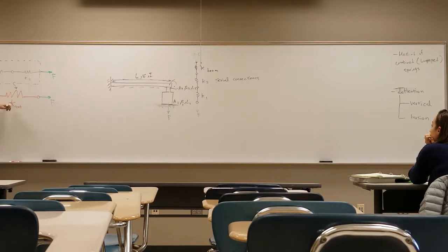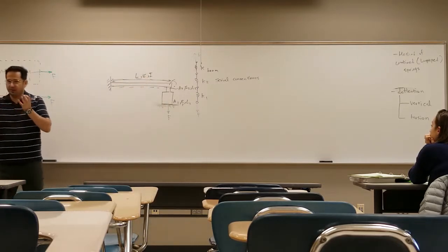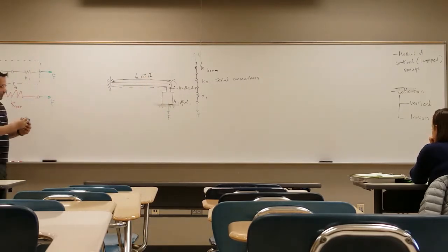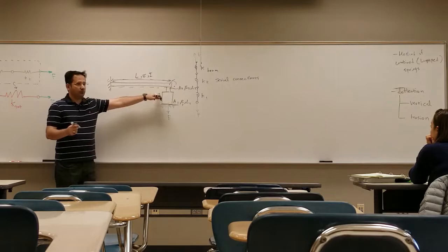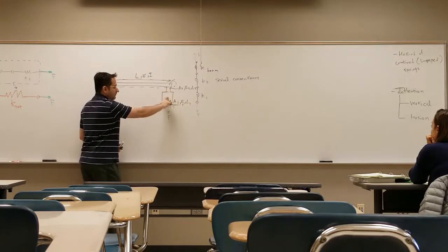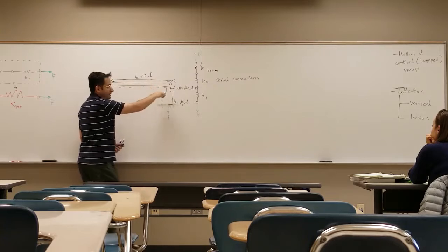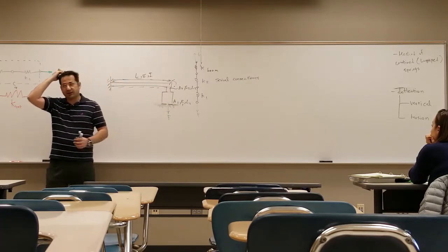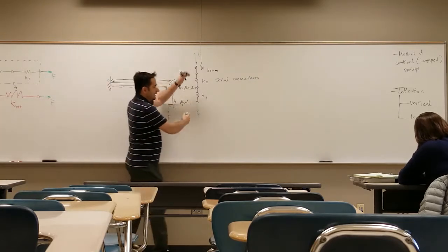Here are two springs. I want to combine them into one spring. That's the reason we say method of combined springs, because you can reduce a complicated structure into a simple structure that you can analyze, right? So before we actually go to that, we want to solve this problem using the actual deflection. Say deflection here is a combination of deflection coming from this bar plus deflection in this bar plus deflection at the end of the beam. If you do that, then you can find the deflection. That's one method, and find the equivalent spring constant.